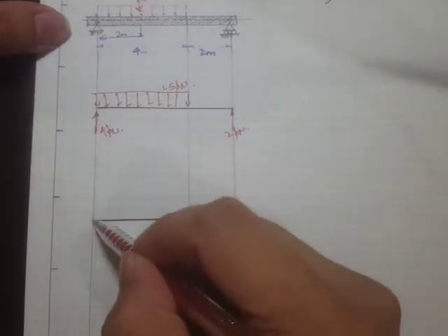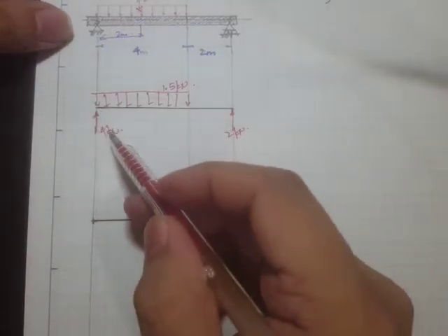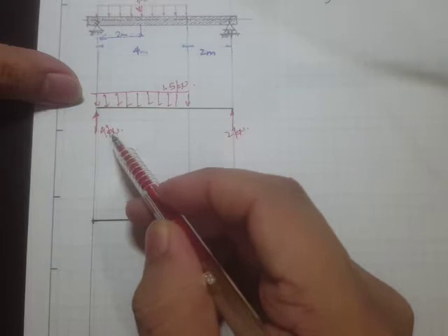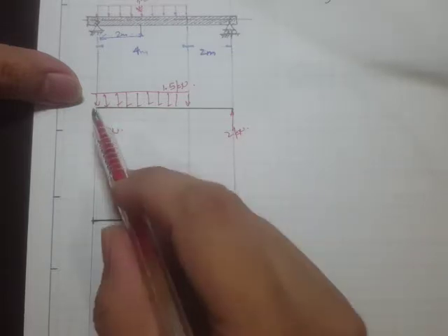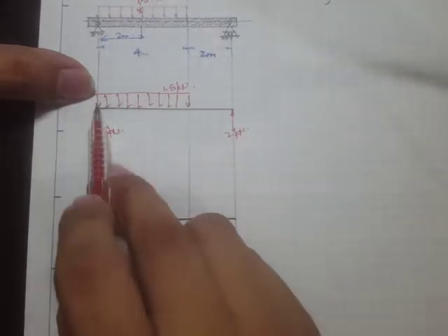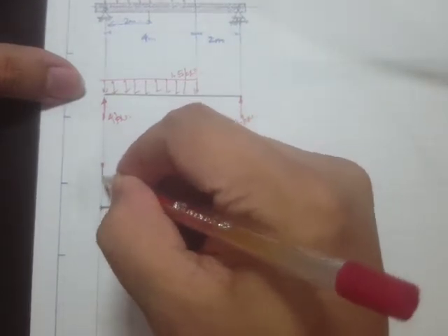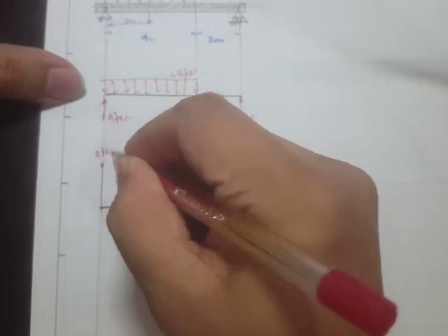Okay, so at point A, it says here that there is a concentrated force of 4 kilonewtons, and there is also the start of the distributed loadings. However, at this point, this is 0. The distance here is 0, so therefore 1.5 times 0 would just be 0. So what matters is this concentrated force. So it says go up 4. Let's say this is it. So 4 kilonewtons.